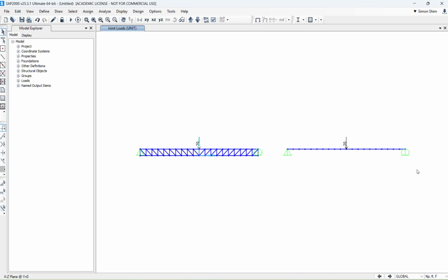So basically this is the beam versus this truss. The difference, or the same thing, is we are using W18 by 35 as a default. So this guy is the beam, but for the truss, since we have only one section property, every member is going to be W18 by 35, which is not an apples to apples comparison, right? But for analysis, we can just let it run.